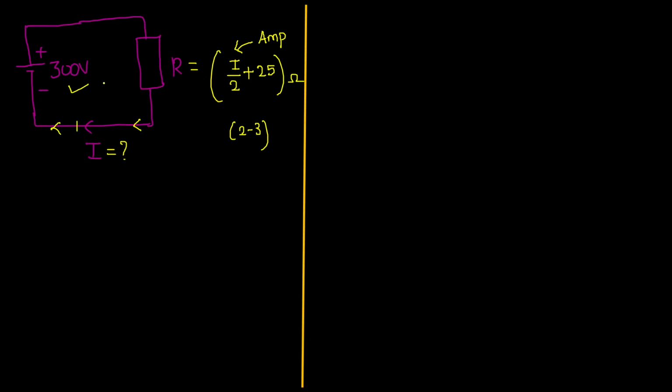Okay. Whatever direction they have given for the current, what do we know? By default, whenever our circuit is having only one independent source, in that case that one independent source is going to deliver the power. I already told you, you need not figure it out, that will be the solution for you. If you are having more than one independent source, in that case you have to analyze which one is absorbing and which one is delivering the power. But in our case, the given circuit is having only one independent source, so definitely this independent source will deliver the power by default. First conclusion.